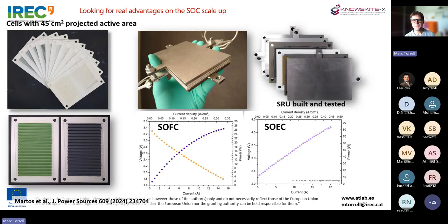We join 3 single repeating units of these very simple interconnects and 3 of these solid oxide corrugated membranes, and we achieve in fuel cell mode at 900 degrees already almost 28 watts per substack, and in electrolysis mode we achieve the 83 watts of power of this electrolyzer, injecting already 20 amps to each cell.